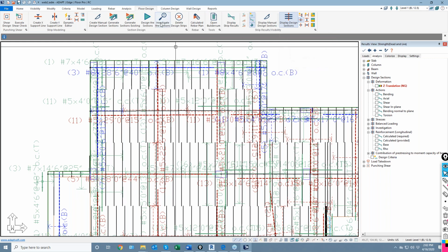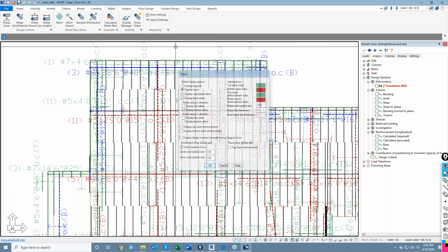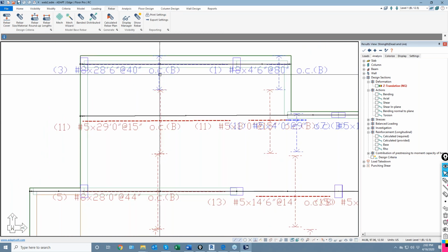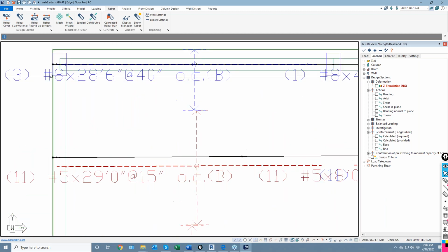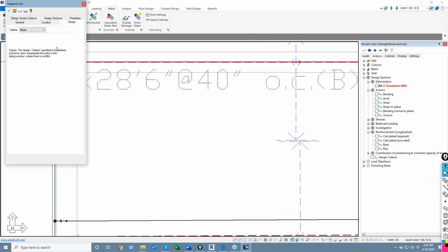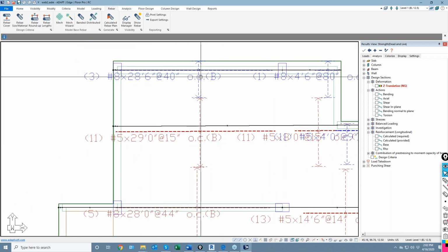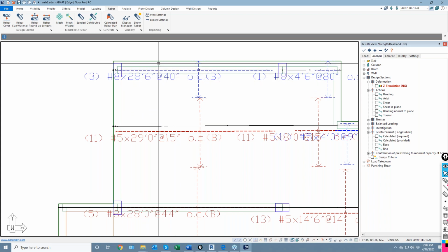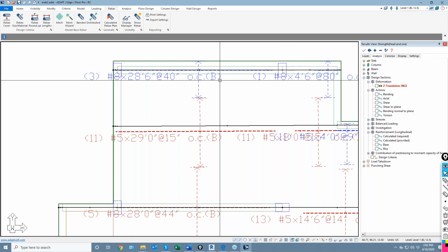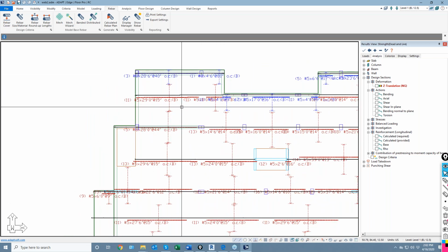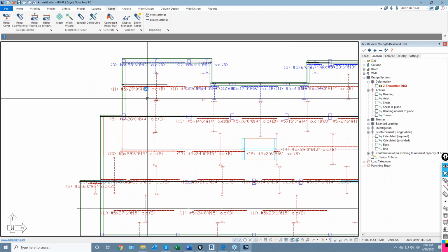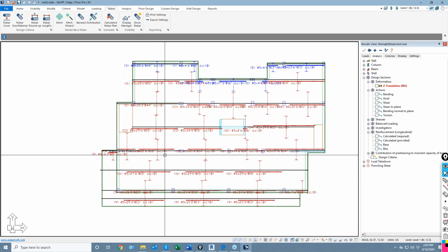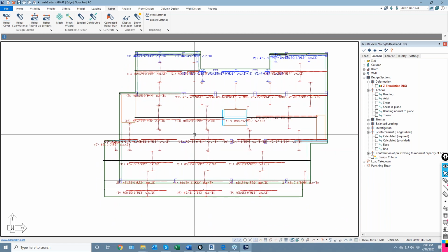Okay, and you can see, let me just toggle this again. This bar is changed to 8. In this case, it should be shown as a piece of grouped rebar. Let me make sure. Yeah, that's still shown as beam. So something's going on there, but this really should be shown as 3 number 8s by 20'6". This at 40 technically should not be there, and this should just be shown as 1 bar. So I'll have to check that out to see what's going on there. But that's how you can make modifications to design strips and then recycle through the design of those strips.